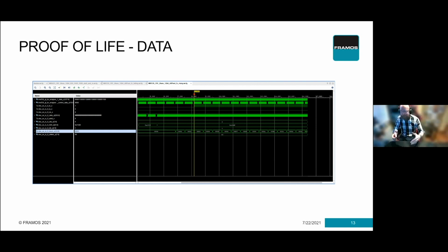But let's just say it doesn't perform well. The debayering and color reproduction for a human's consumption doesn't happen on the sensor, at least not on Sony image sensors. There is no Bayer to RGB conversion happening on the vast majority of the sensors. In fact, all the sensors that we sell, but not necessarily all of Sony's. And what that means is that there are processes that are creating the color afterwards. You have to give good information in.